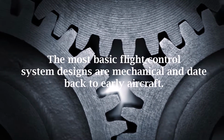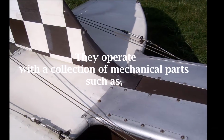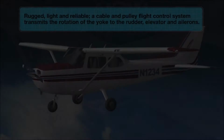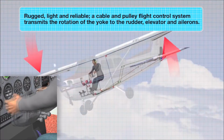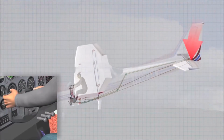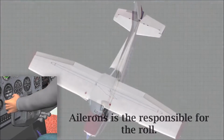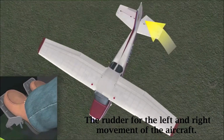The most basic flight control system designs are mechanical and date back to early aircraft. They operate with a collection of mechanical parts such as rods, cables, pulleys, and sometimes chains to transmit the forces of the flight deck controls to the control surfaces. Rugged, light, and reliable, a cable and pulley flight control system transmits the rotation of the yoke to the rudder, elevator, and ailerons. The elevator is for the pitch, or the up and down movement of the aircraft. The aileron is responsible for the roll, and the rudder for the left and right movement of the aircraft.